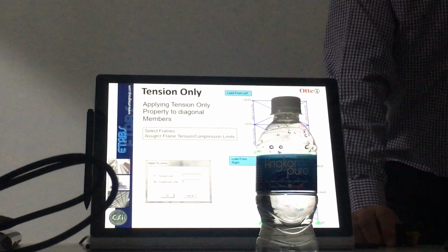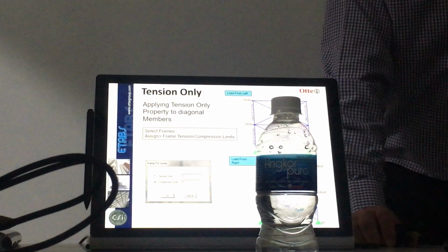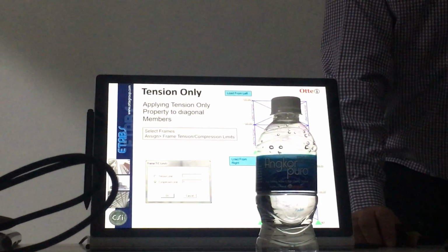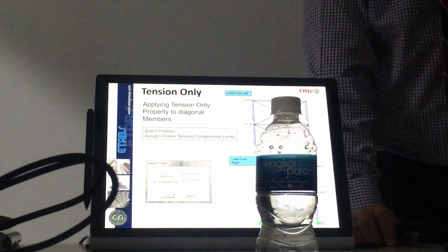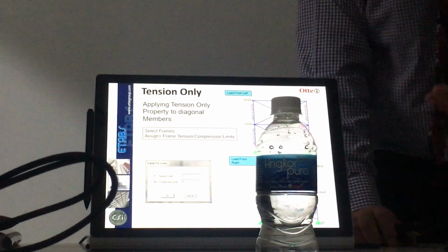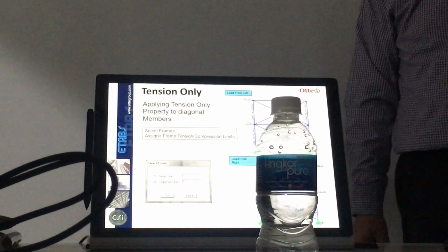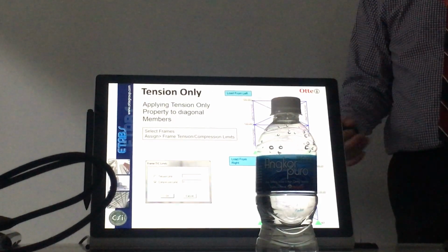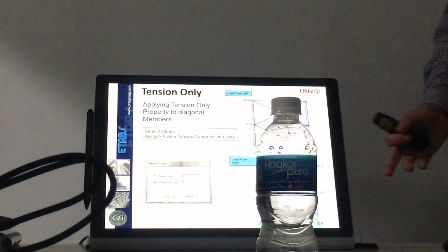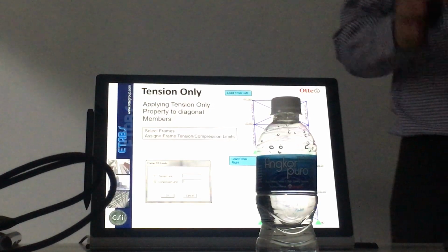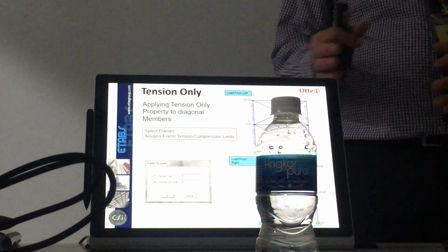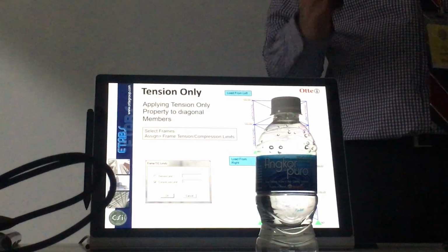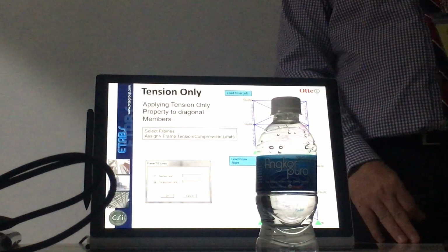So when you have a non-linear load case, means that you cannot do superposition. It's not a problem for you because you're doing direct analysis method anyway, right? Because direct analysis method always have to explicitly define for each combination, right? So that is not a problem. But in the past, when we don't do direct analysis method, when you do effective length, you actually do linear analysis. So if you do linear analysis, this effect may not capture.